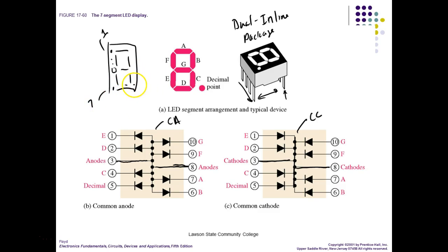Then you come across, straight across, and then the first pin on this side would be pin 8. Then you start counting. If you see a space, you count it like a pin was there, right? Does that make sense? And then you'd go up, and the top pin up here would be pin 14. And this is what we call a 14-pin dip package. Even though there's not 14 pins there, it's got the standard spacing that would allow 14 pins to be there.